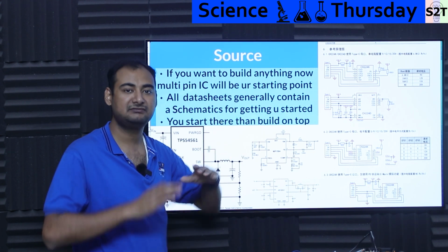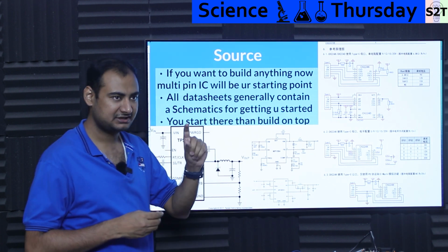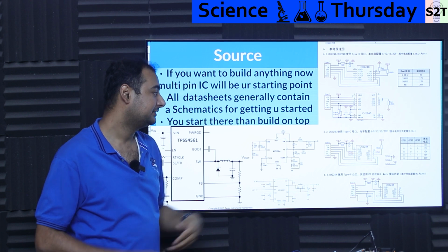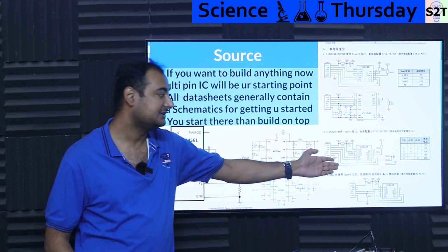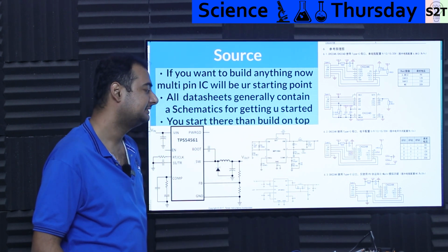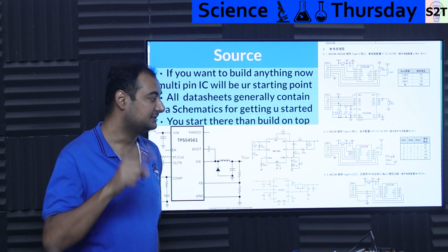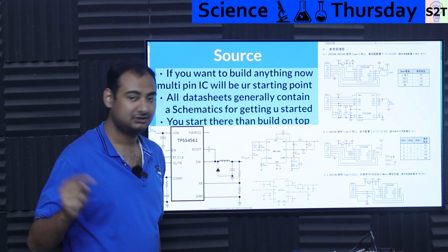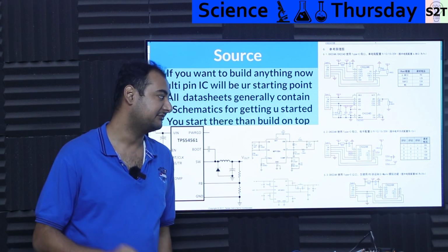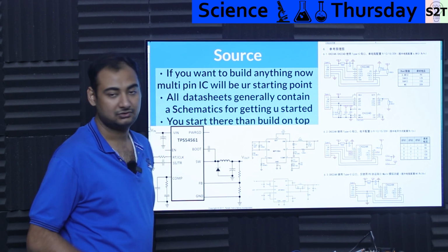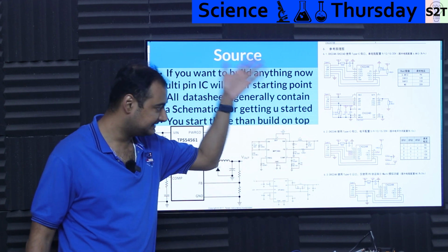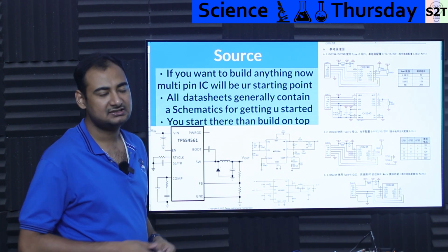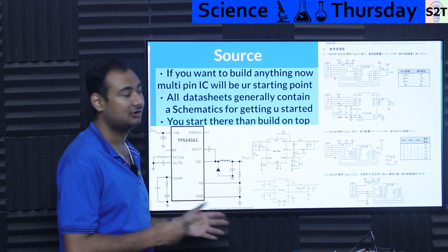Again, this same design will go into other manufacturers. Some boards are just fixed voltage. Other boards are configurable. For the configuration, they are giving a very easy example where you have a lookup chart. If it's 100, it's 5 volt. 000, 9 volt. 001, 12 volt. 011, it's 15 volt. 010, 20 volts. So that's how you get it. This is generally the starting point, be it simple devices or bonkersly complicated devices, that's how it starts.